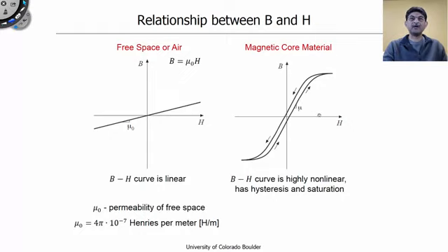However, when the applied magnetic field is so large that all the magnetic domains have already rotated, then any further increase in H will only result in B increasing by mu naught times the increase in H. Hence, the slope of the BH curve, once it hits saturation, is going to reduce to simply mu naught. The reason for the hysteresis in the BH curve is due to the energy needed to rotate the magnetic domains. We will explore this further in a later lesson.